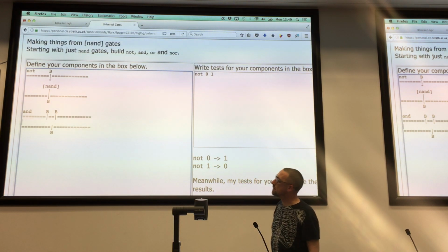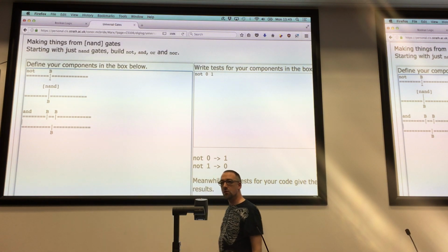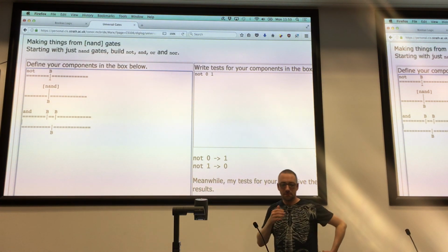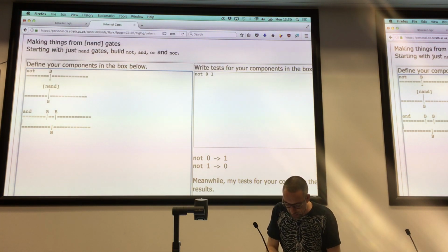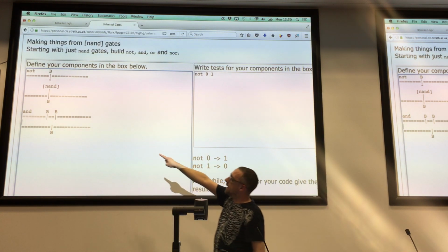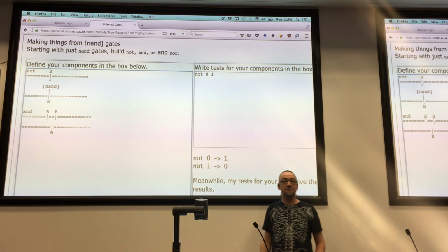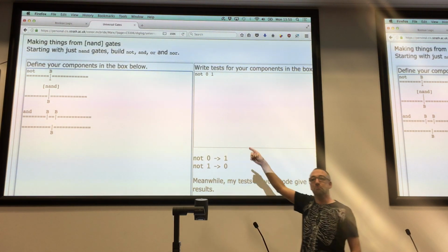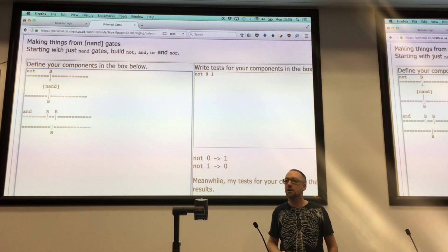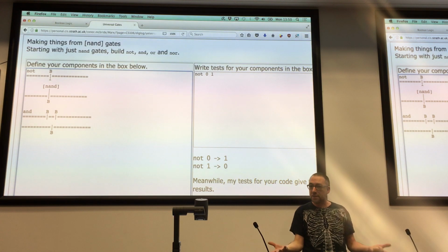So we're saying AND is this picture. We're not making a formula that has an AND in it. So it doesn't matter what letter you use. Input labels: these inputs are labeled B because what's coming in are bits. B here stands for bits. We're saying there are 2 bits coming in. Later, you'll see H's coming in, which are hexadecimal. So that's saying what the type of the thing is, what its external connectivity is.